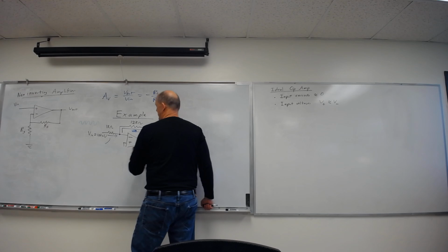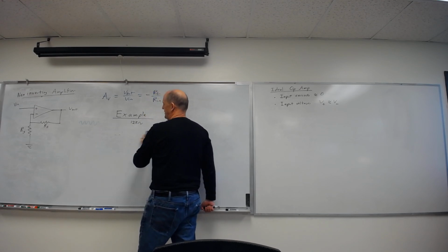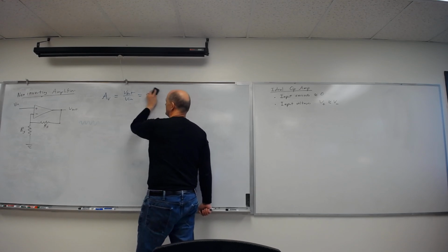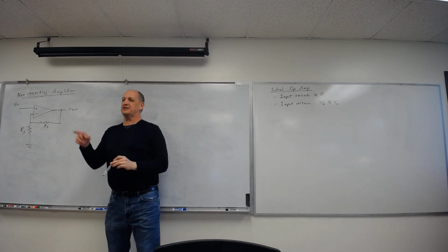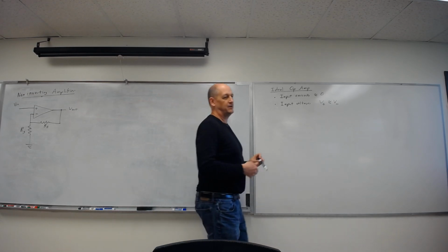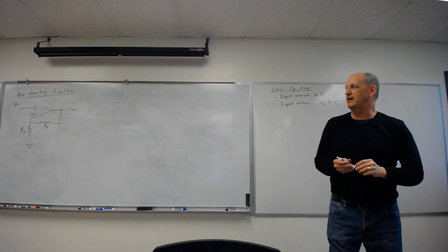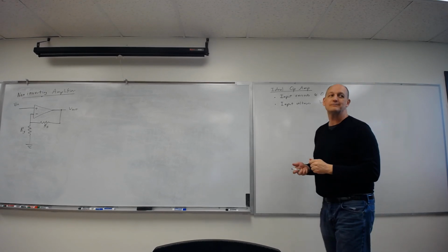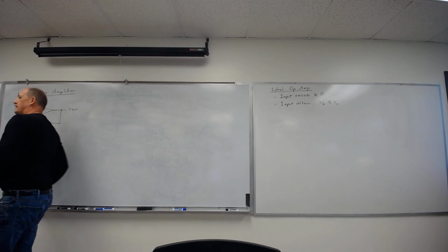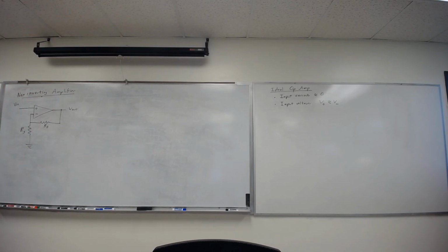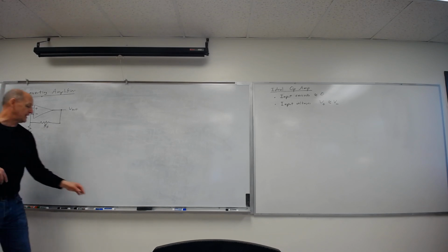Or if I use my RC circuit that we learned from the week on capacitors, then I can make it take time to go up and down, and I can actually produce a sine wave out. So that's how I build it. If you know what LFO is, low frequency oscillator, we can build with that. Next semester, just something to look forward to. So yes, there are places I use positive feedback. We won't be doing it here, but we can.